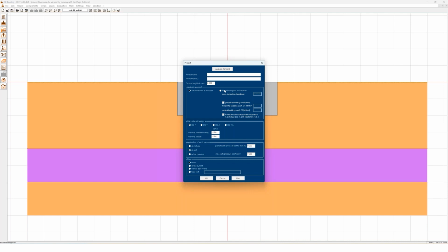Due to the rotation from the bending moment, the earth pressure is activated, and hence the footing is fixed through the active and passive earth pressure.